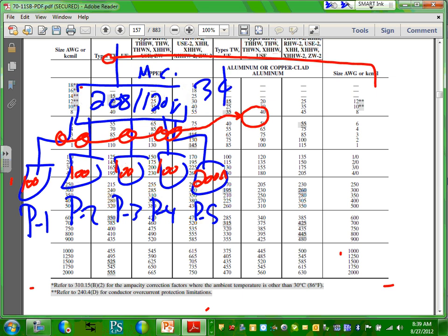Three-phase. Okay, where would you size? Now we moved the system, we made it three-phase 208/120. I can't use the table that we were in, so we're here. So let's go size. First one is 100 amp. Can you size it for 100 amp without knowing the loads? I have no idea what the loads are. For the 100 amp, what would the size be? 100 amp, number 1. Now for the 200 amp, which column would you go to? 75. We just talked about 75.